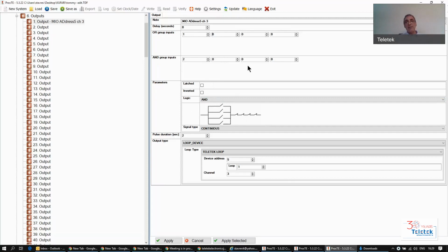This corresponds to the second one, etc. So by putting number 1 input over here on this line that represents this part, as soon as I put a number there, this switch will open up. So now, how is the panel going to react? If the sounders turn on, respectively my input number 1 active, this will close this switch. But the signal will get jumped over here because second part, switch number 2, input number 2 is not active. Unless there is a fire in zone number 1, and then this input is going to close, and the signal will go to the other side to my output module.